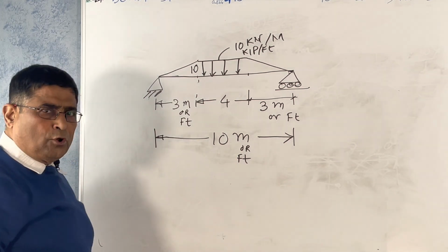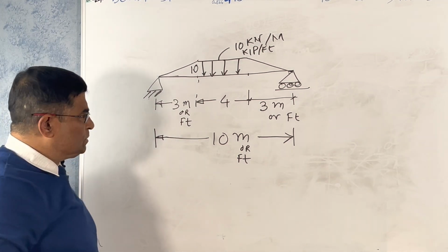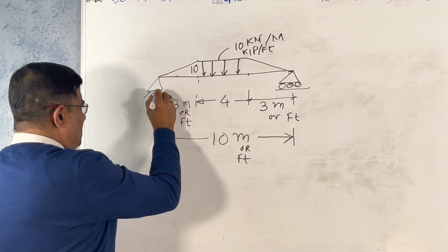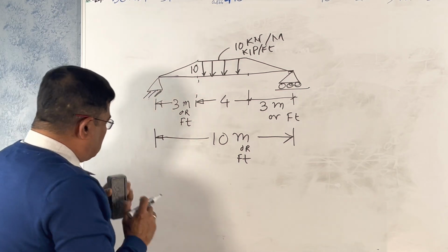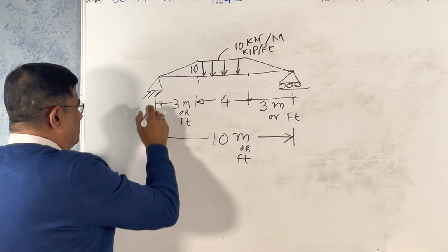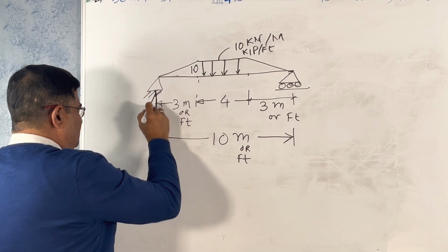Now, if you have to draw a bending moment and shear force diagram, first of all you find out the reaction. What is the reaction?